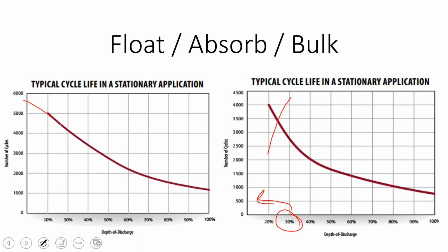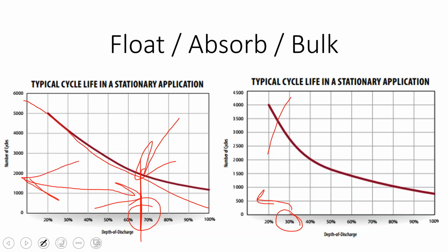But if you use an industrial forklift lead acid battery, which costs a lot more, this strain curve may not begin to bend until a 65% depth of discharge. And so you might actually discharge the battery much deeper than you would normally. Now, this is assuming a steady, constant discharge rate that you can accomplish through good appliance selection.